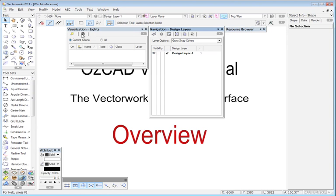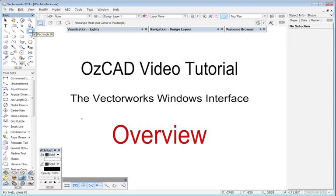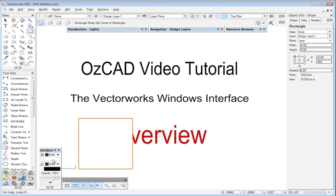The visualization palette is where I can control the lights in the drawing, and if you have RenderWorks, also the cameras in the drawing. Here we have the attributes palette, and the attributes palette allows you to control the fill, color, style, and line weight. Let's begin by drawing a rectangle here, and it has a solid fill already.